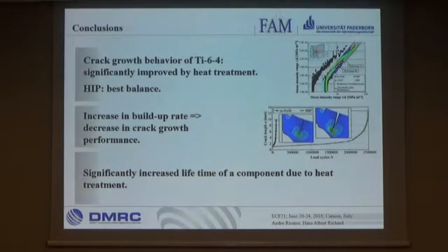So let me summarize the major conclusions. The heat treatment has a significant effect on the fracture mechanical data, and the HIP was here with the best balance of mechanical and fracture mechanical properties. The increase in the build-up rate shows that we have a decrease in the threshold value. That means a decrease in the crack growth performance. And at the end, we found out that the lifetime can be significantly improved only by removing the residual stresses.